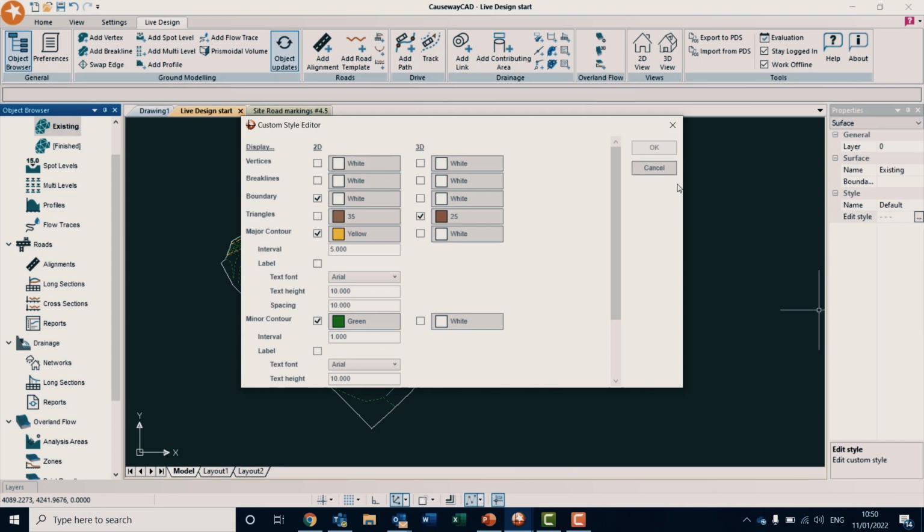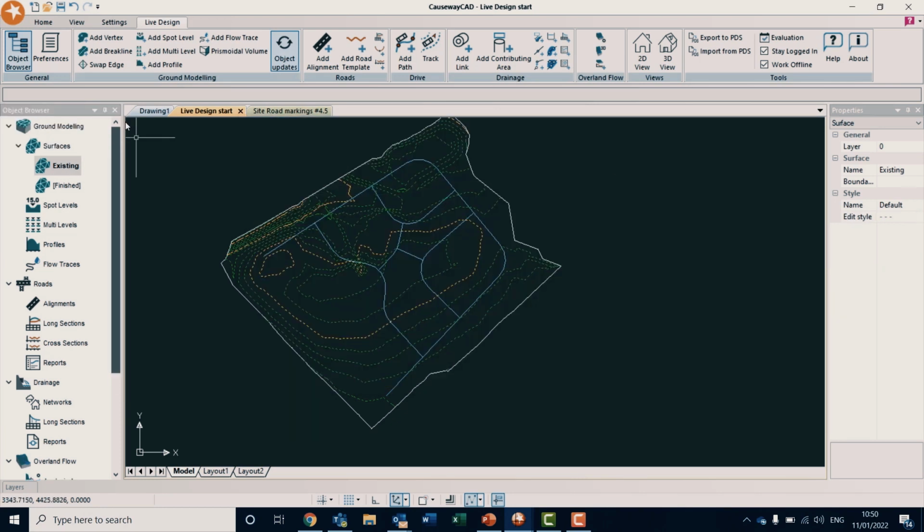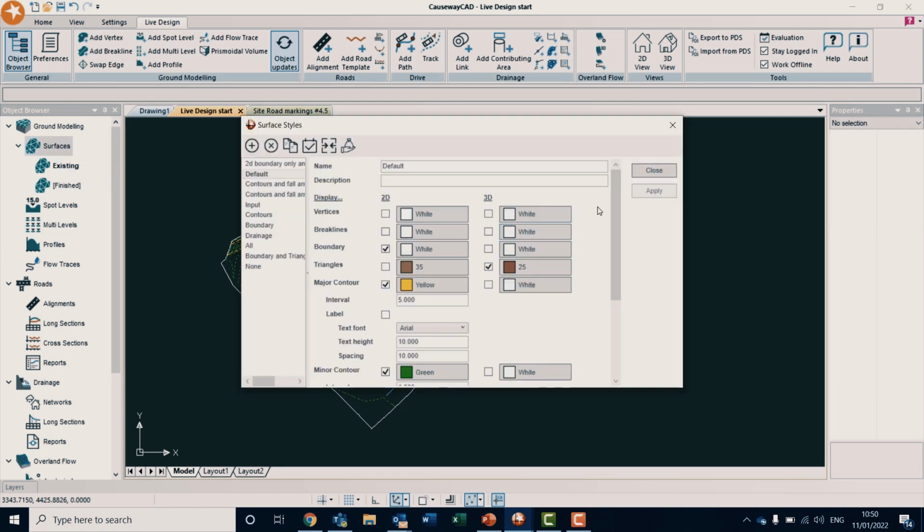And this defaults to the contours, but you can then go in and look at the different styles that you've got. You can either do it globally within the styles within the surfaces. So you go into the styles there, and here you can see we've got a range of different contour styles. That's really good because sometimes civil engineers don't work with the same color styles. So this will stop that problem, so everyone can import the same styles. And as you said, with different clients, you can import the different styles they want.